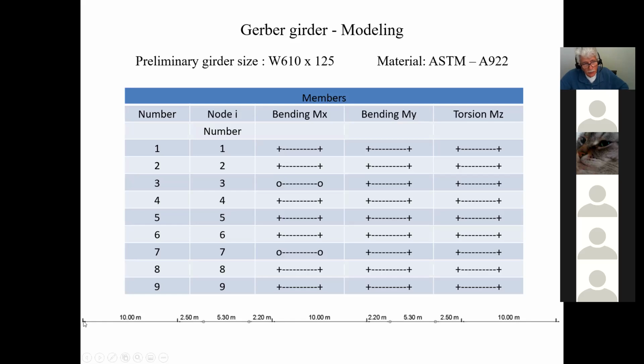So in other words, you're going to have a pin, roller, roller, roller, roller, roller, and then this member here is fixed, and fixed, so that fixity is what makes it continuous, but I still have to create 2 members there. I pin the suspended one, so I don't have to pin there and pin there. I don't have a circle there and a circle there, and so on. Of course, if I have 10 nodes, I end up getting 9 members. It's always n-1.